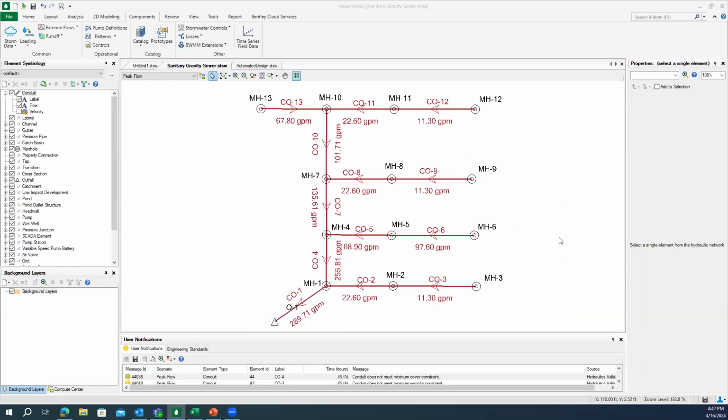This is the base thing that is required first within SewerGEMS. There are some things we have to do initially, like selecting the catalog, conduit, or prototype, but everything could not be covered within the webinar. So this was the base workflow that could be followed, so that you can have a basic idea of how SewerGEMS could help for sewer networking and modeling.